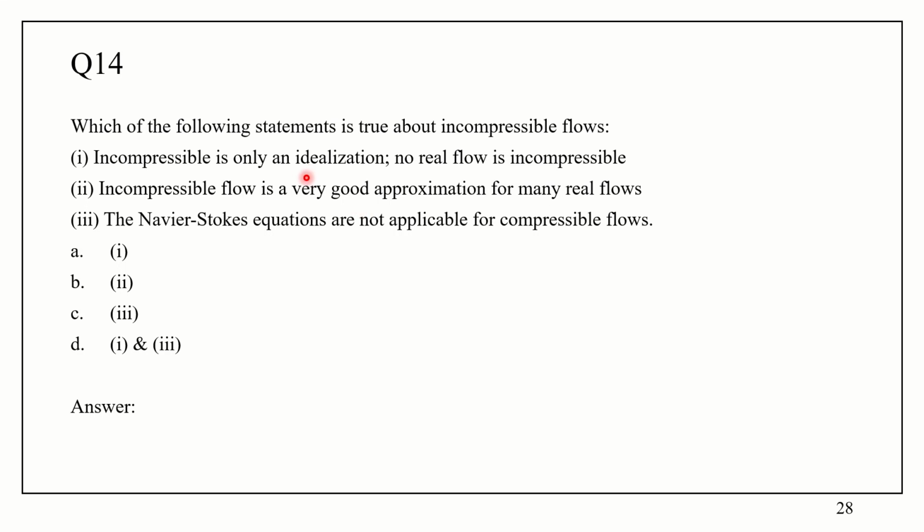Again, this is true. The second statement is true because most of the time we can approximate it as an incompressible fluid, and density is not varying, so we can take it out as a constant and simplify the equations. Whereas the third statement, the Navier-Stokes equations are not applicable for compressible flows, is false. Navier-Stokes equation is applicable for compressible flows. So the first and third are false, the second is true. So option B is the right answer.